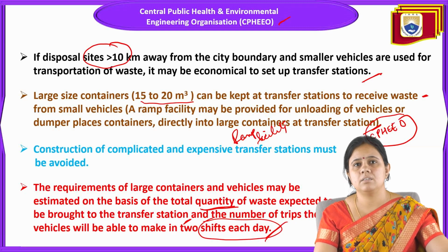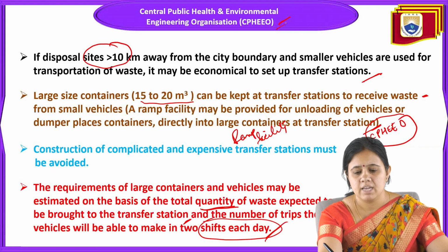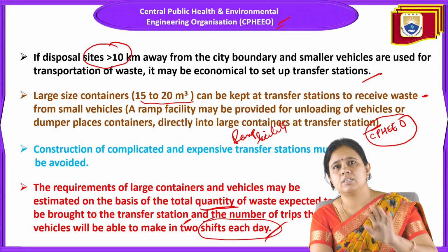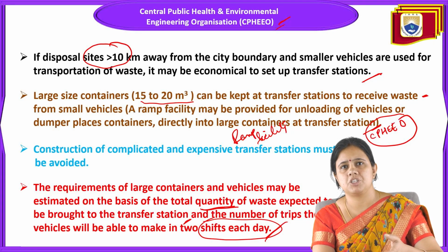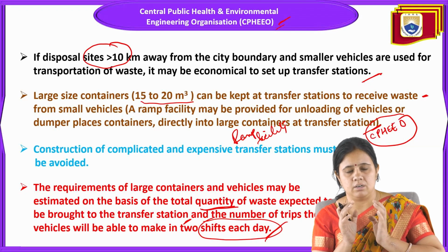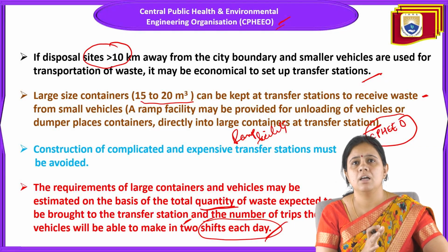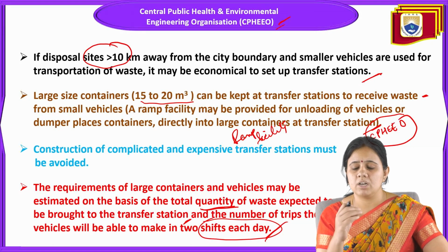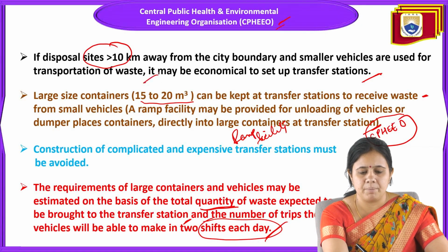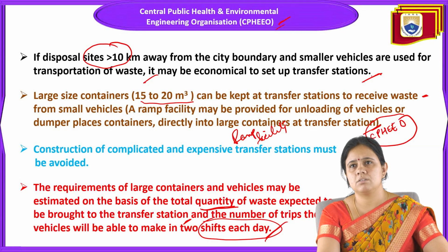This organization has made everything clear regarding the disposal site, the material recovery facility site, the transfer station, and the containers used. First of all, the disposal site should be available within 10 kilometers of the city boundary, and even smaller vehicles can be used for transportation of waste. And it may be economical to set up a transfer station. Means, to set up a transfer station, it should be economical also.